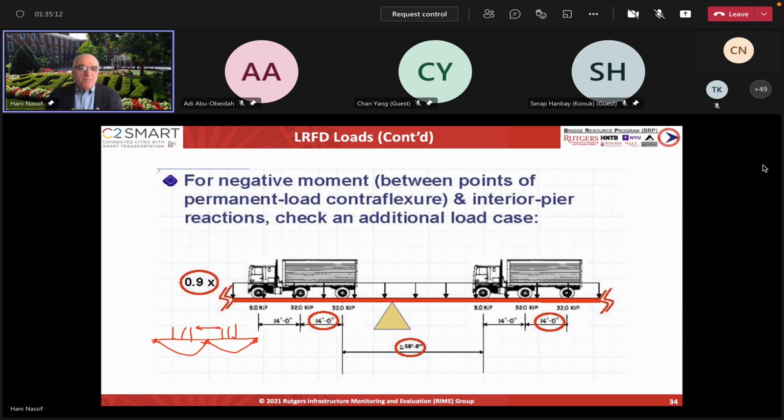The headway, maybe now in traffic jam, it will be shorter than that, right? But then you will be away from where the maximum moment is. So 50 feet, usually if you have spans, each 100 feet, 50 feet is reasonable to do that. And then that will give you the maximum moment, and the uniform load is applied on all the spans at the same time.